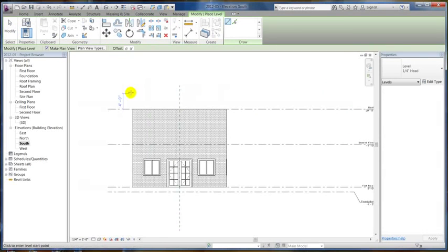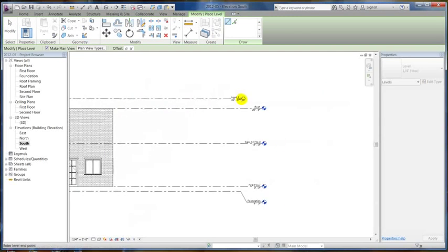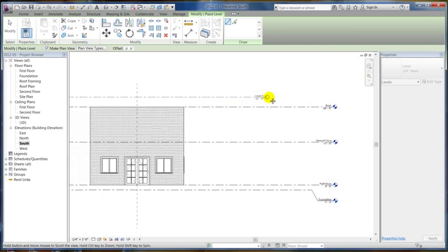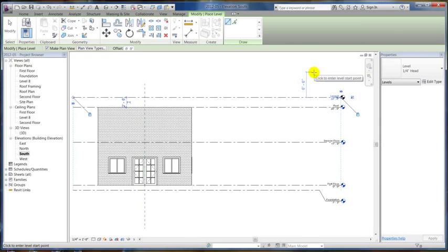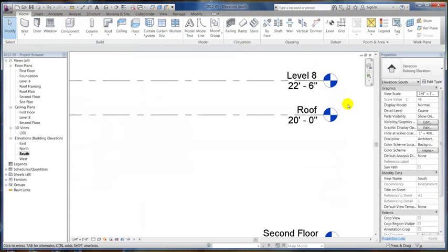And I'm going to go ahead and draw a level. Let's just draw right here. The level head comes in second, so that's why I picked over there first. I just know from experience the second pick is a level head. So there's my next level.